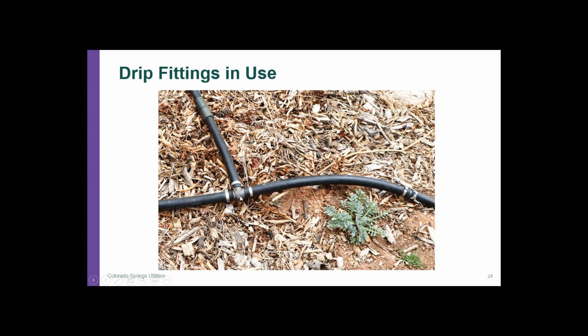You can see here we have that barbed T, where we're connecting at an intersection of 3 pipes. I have one pipe coming from this direction, another pipe coming from the left, and we have this pipe extending outward. We've used a T here, and we've used these clamps, and we've clamped around that barb fitting. I like to move these clamps as close to the very last barb as I can, just to make sure that this pipe is going to definitely stay on that barbed fitting.